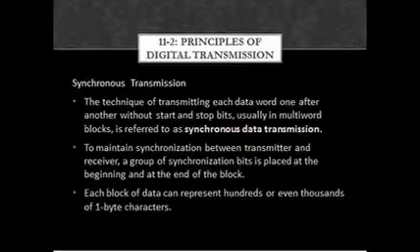Synchronous transmission. The technique of transmitting each data word one after another without start and stop bits, usually in multi-word blocks, is referred to as synchronous data transmission. To maintain synchronization between transmitter and receiver, a group of synchronization bits is placed at the beginning of the block and the end of the block.